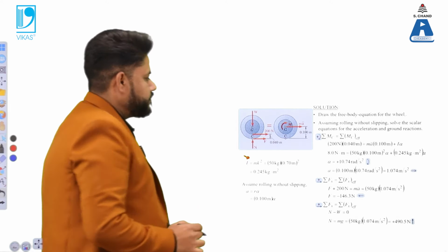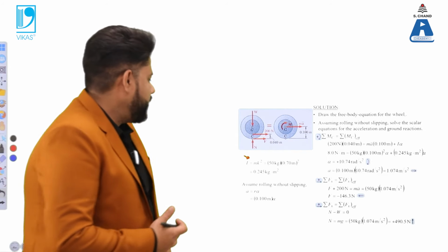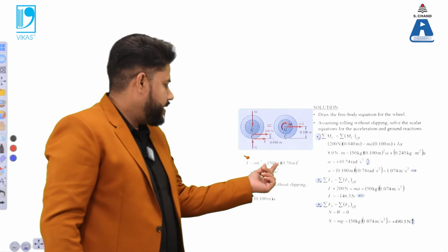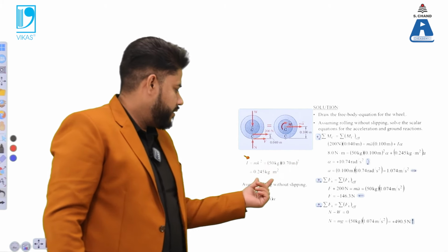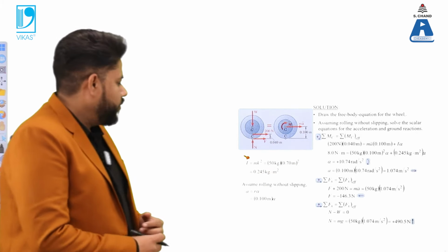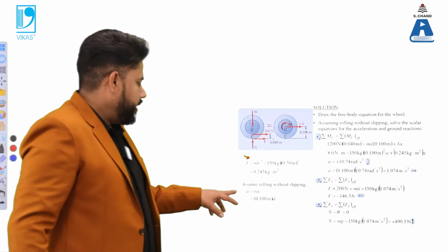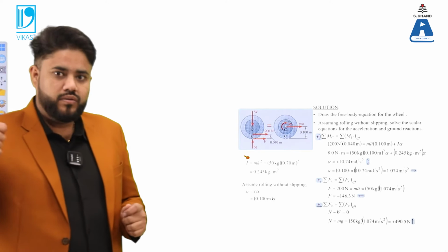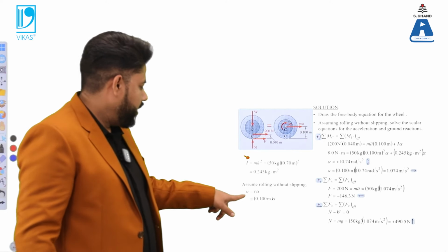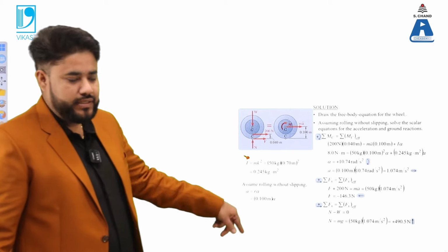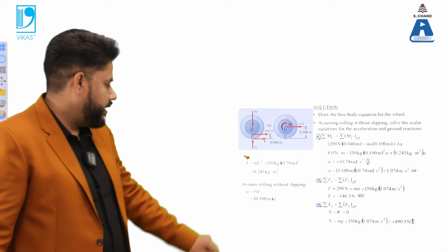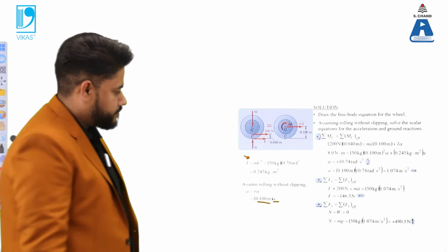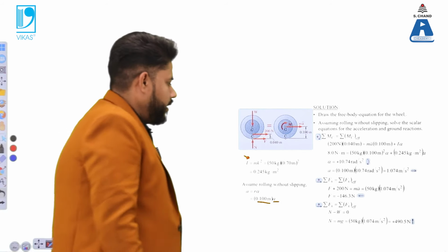So how to calculate that moment of inertia? That depends upon the radius of gyration. So I equals mk squared. 50 is that mass, and the k value is this. You can substitute that value and you will get the moment of inertia. Additionally, we assume that there is no slipping, because we are pulling that rope from the surface. The acceleration component can be obtained from the angular acceleration. So a equals r into alpha, r is mentioned to us and alpha we can calculate.